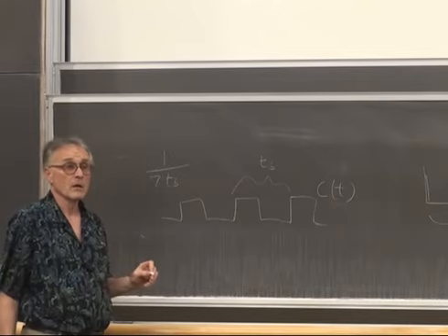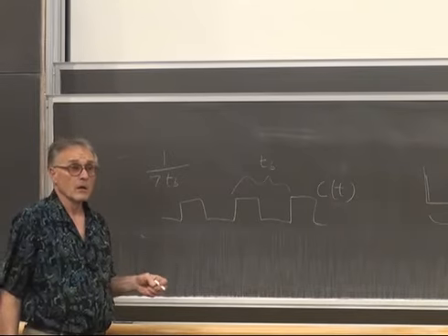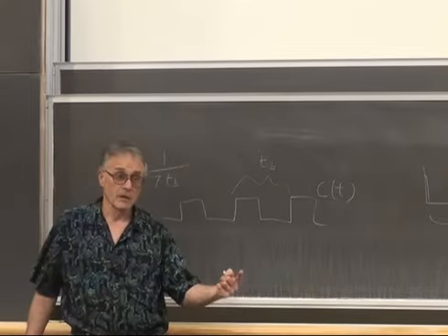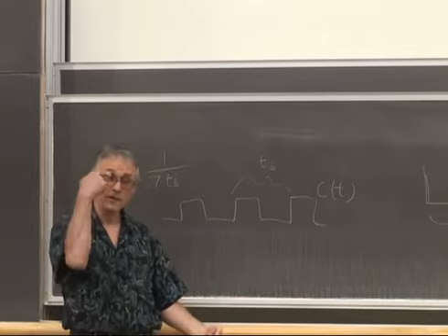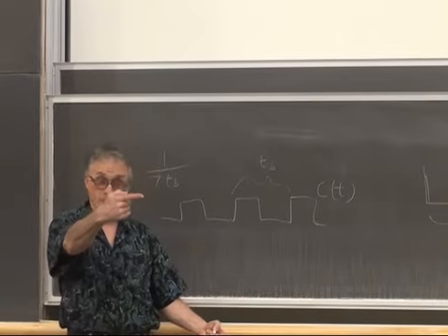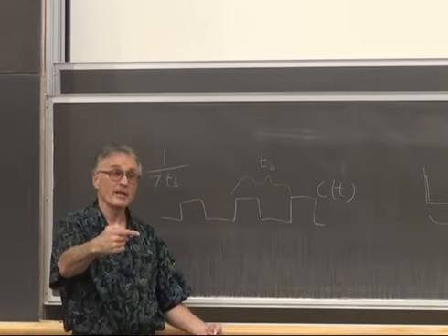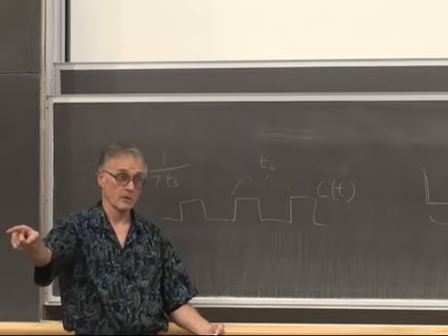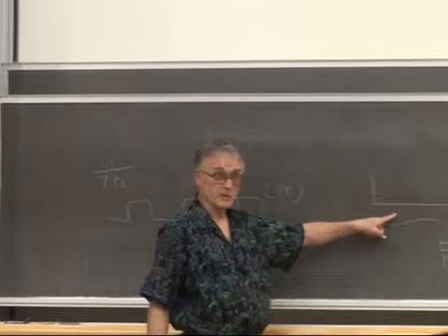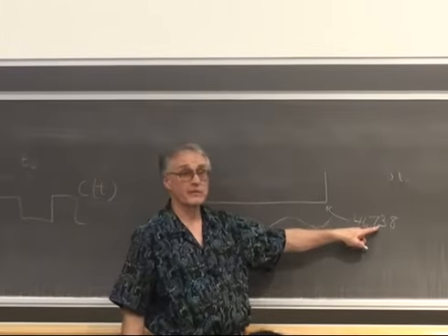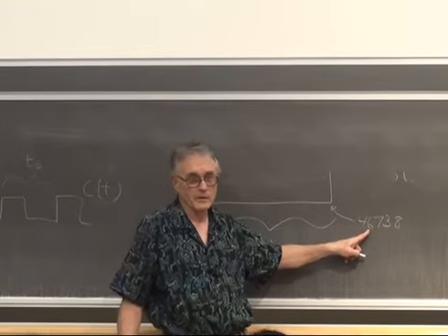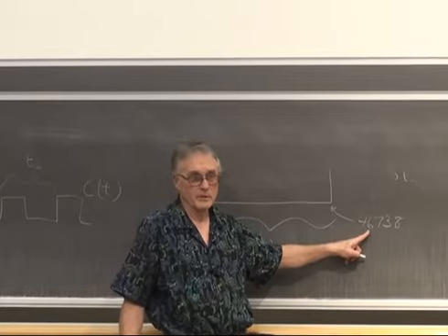I'm asking you to do this conversion in software and convert that RPM, the value you put on the TFT, 2200, whatever it is, you then need to copy into a PWM channel and output to the scope. You're going to use the same timer, so you're going to have to scale that to 46,738, if that's what you choose for some unknown reason for the timer period.